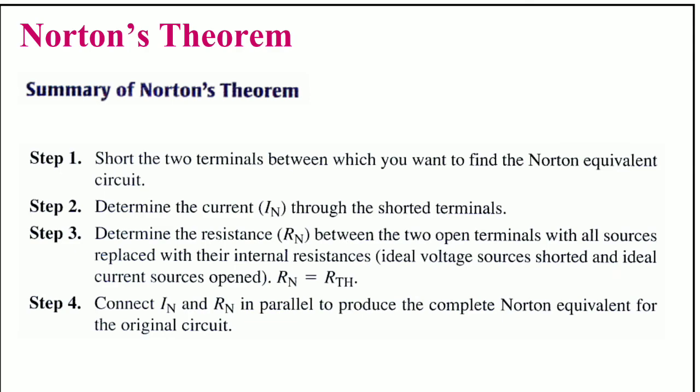Here Rn is equal to Rth, because the procedure for determining Rn and Rth is the same. Step 4, connect IN and Rn in parallel